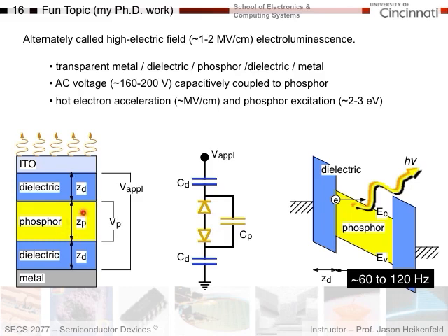So if I'm below the breakdown voltage, there's no breakdown, and I just see this capacitor here in series with the other two capacitors. But if I go above a certain voltage, these will start to break down, and I will get current flow in between these two capacitors. The reason why I have these two capacitors is so this current flow doesn't run away. If I put a high voltage here, I'd like to break these down, but then have the current be limited by these capacitors.